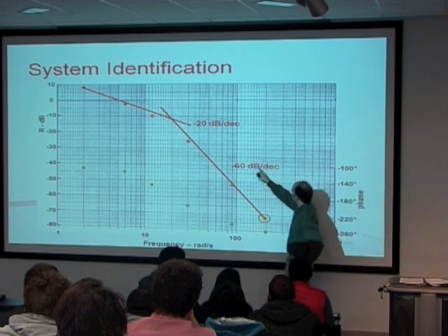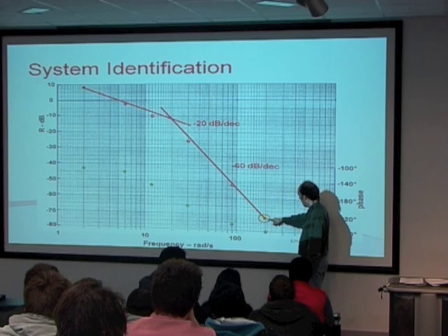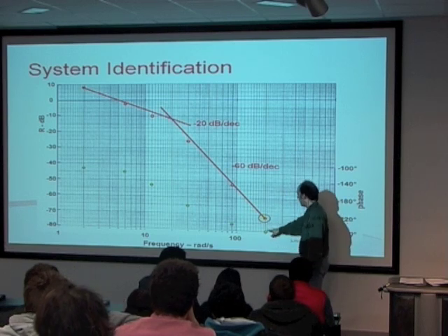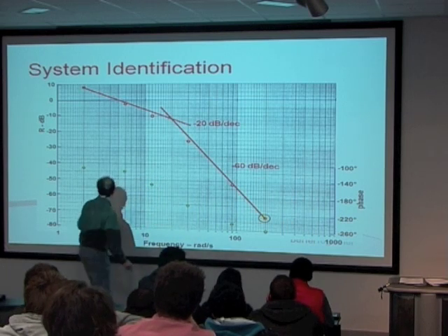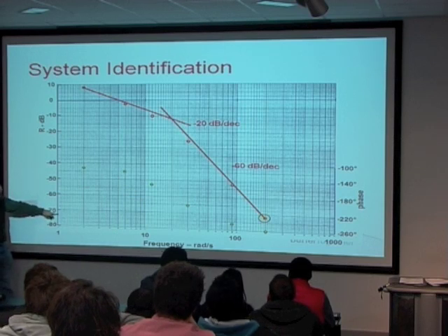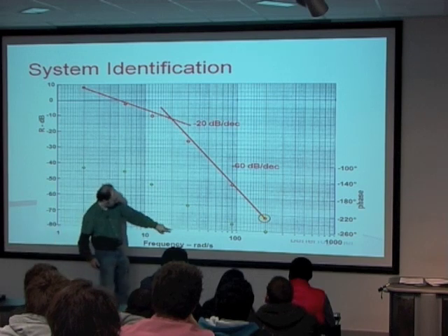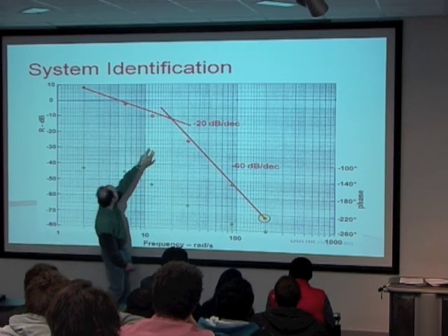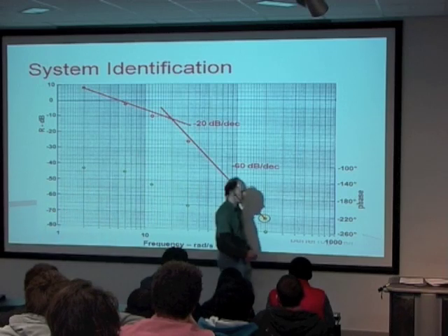And notice with minus 60 dB per decade, well, basically, that's a scale in decibels. And so in 1 decade, this is some 200 hertz. 1 decade down would be 20 hertz. Notice that minus 60 would be 60 on this scale, and we're down at, what, 72 there or something. And so minus 60 minus 72 is about minus 12, isn't it? And you can see that at this frequency, which is 1 decade down, we're about minus 12 on the scale. So that's how you get 60 dB per decade. It's a straight line.